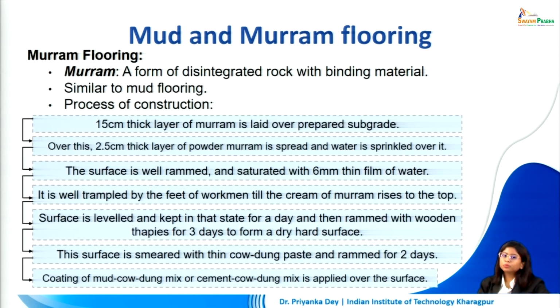If you are dealing with muram flooring, muram is a form of disintegrated rock with binding material. It is very similar to mud flooring. The process is slightly different. Here we have a 15 centimeter thick layer of muram which is laid over a prepared subgrade.